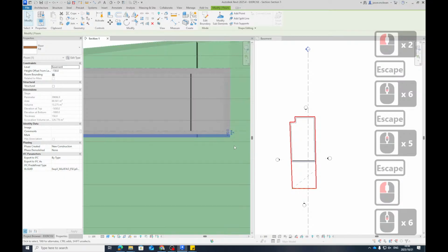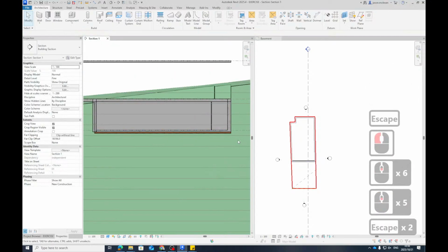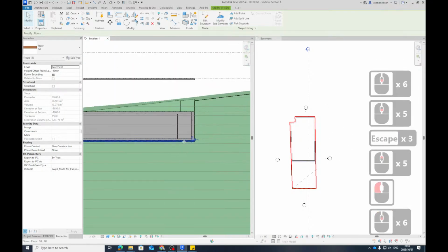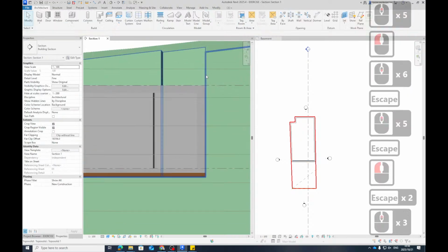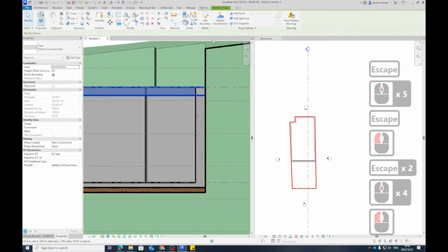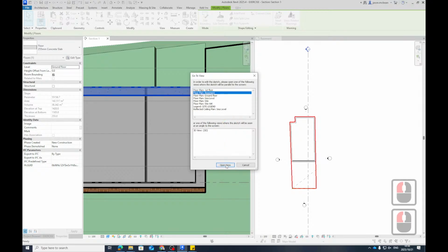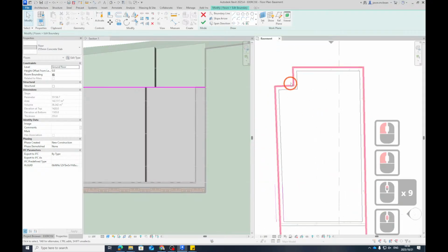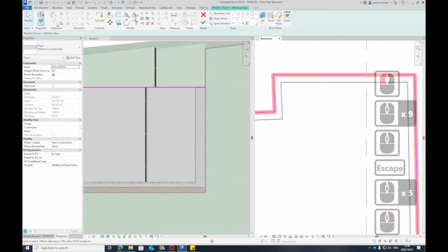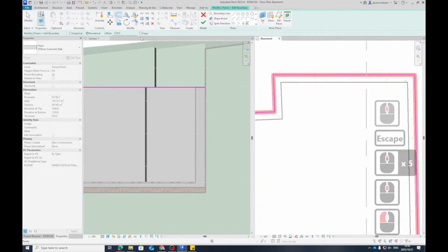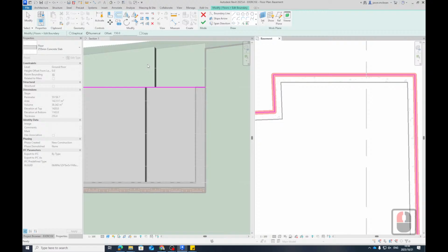And that's why I use the fill to go past, so that this fill now drives my excavation and not the floor slab. So you can use your floor slabs correctly. Likewise with this floor slab, if I go and say edit boundary, again I can just say basement, it's open already. So this I want to use again, so I can say offset. So this floor slab will join to this concrete wall. So this becomes like a concrete basement foundation. So your floor slab above will connect to this wall, and then the brickwork starts up above. Okay, and I'll show you that now.